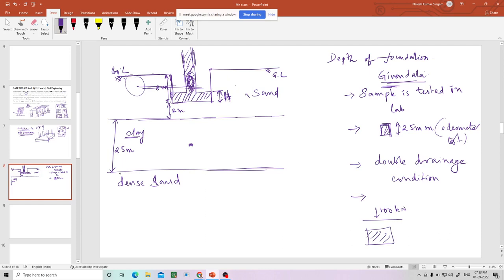Okay, let us say this is 100 mm. You are giving this much load. These are random numbers, don't think that these are existing in the real field condition. When you are applying the load, this gets compressed, it will become 90, then slowly 80. At one point, maybe after becoming 70, it might stop. After that, this load will not decrease the height or volume of the soil sample.